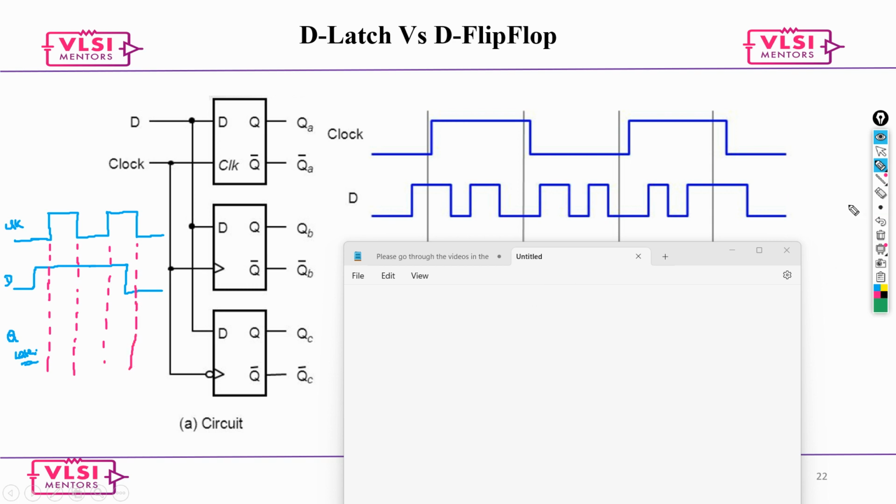Now say this is high, here it is high, and here it goes high to low. What you need to do is connect this high like this, and then continue this zero. This is how your latch works. Anything during this positive window will be copied over as it is, and the last state would be carried all the way till your next pulse.